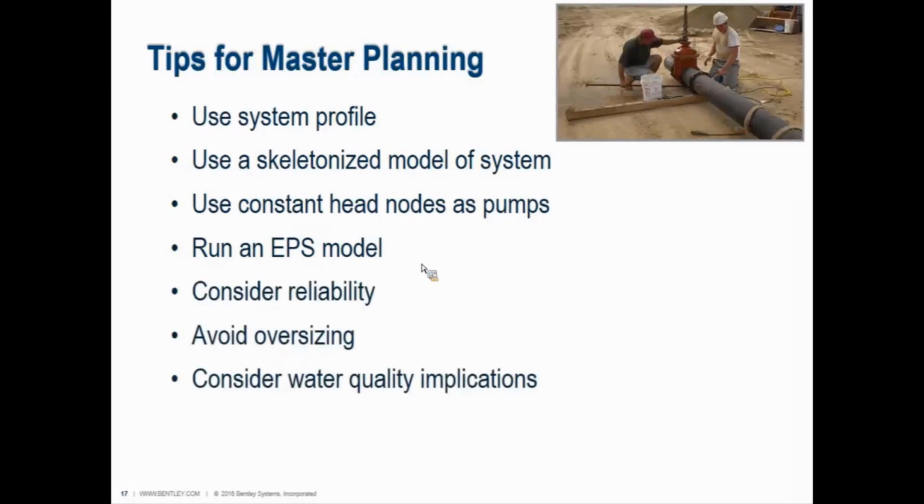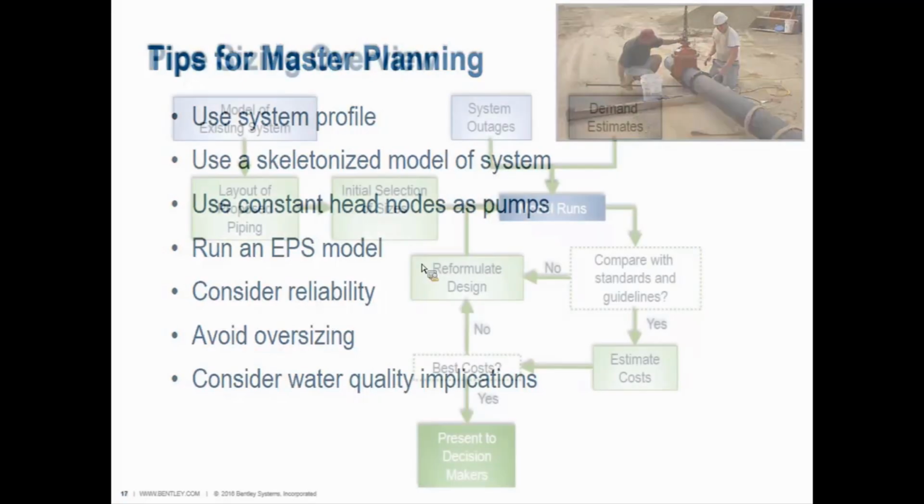You can start to consider water quality implications with a master plan. However, you're not going to have as many loops and as many connections with a skeletonized model, so that's going to be a little bit of a tough one to accomplish. Pipe sizing.